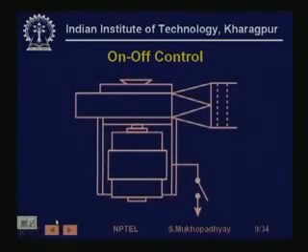Similarly, another major application for flow control is cooling. It is not good if sometimes you send coolant and sometimes you do not, because then the temperature on the equipment will be pulsating, and this temperature may affect reaction rates and may cause thermal stress on the equipment. So in general, for industrial flow control problems, we cannot tolerate such pulsations. Therefore this on off control method is not good. So we go for other methods.